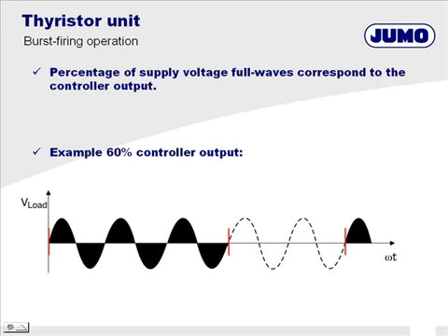A disadvantage is the voltage fluctuation on the power line. This happens when the supply feed does not have a sufficiently low impedance. This effect, known as voltage flicker, causes unpleasant variations in the light intensity of any lighting installation that are fed from the same supply. Otherwise, this operation is unproblematic.